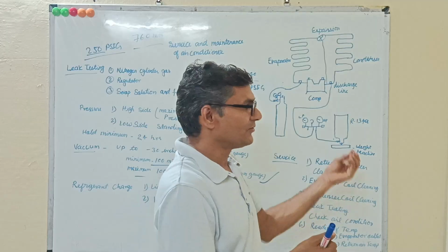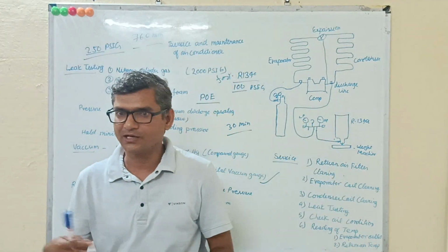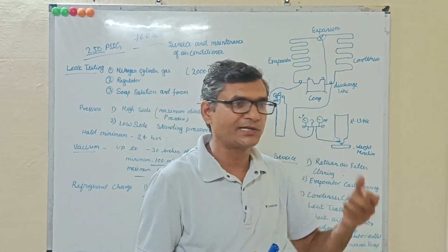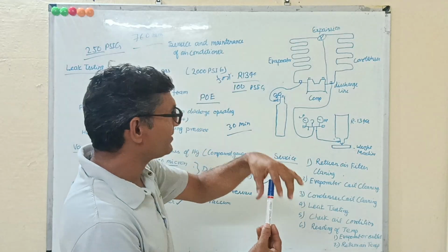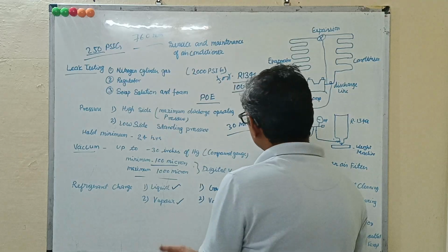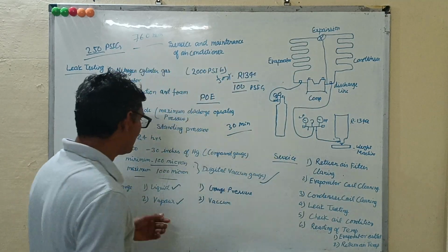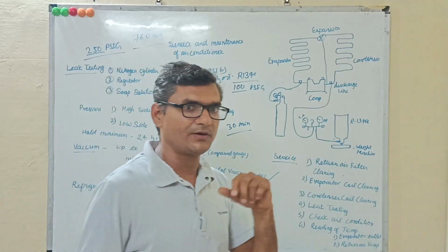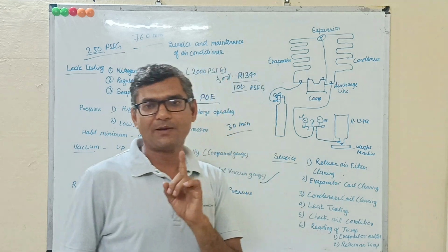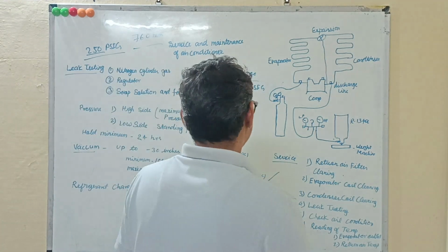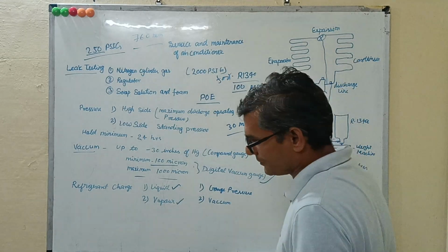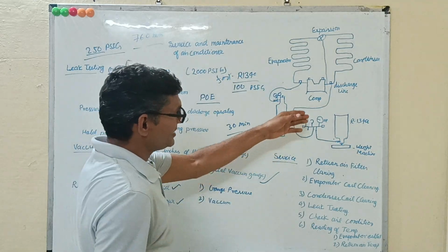We will not vacuum first and then put in oil; that is not correct. We will have to do the vacuum procedure with the vacuum switched on continuously, and here we give the oil drop, and it will automatically suck the oil into the system. Okay, oil is over, then vacuum on, then again two things. Suppose we want to do liquid charge, then only the liquid line size is applicable to liquid charging. Then for liquid charging, at the air condenser side, if any port is given, we will charge liquid here, no problem.